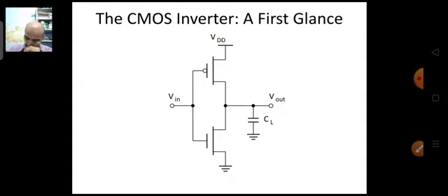But before that, we will see how to get the voltage transfer characteristics, because up till now we have seen a driver and we have seen the VTC in general form. Okay, we have not seen how to get the VTC basically. But the VTC which we'll try to get here is obtained from the basic fundamentals. These fundamentals are related to your load line analysis.